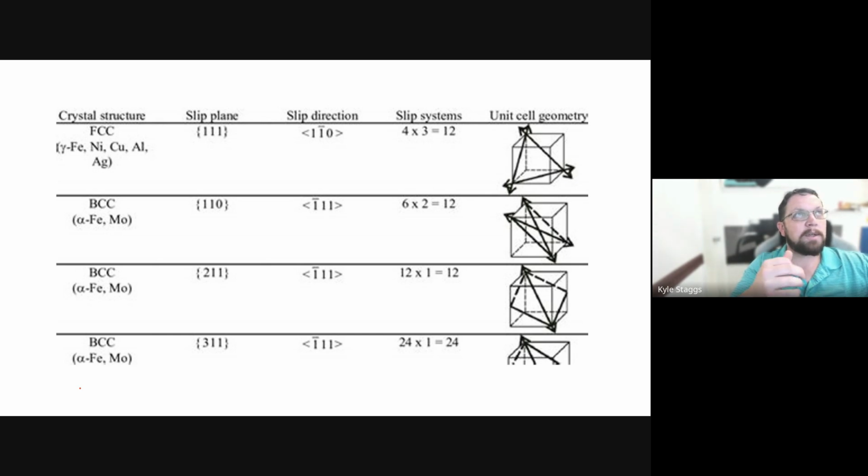But it's actually because of the jagged serrations that are going to show up at the edges of those materials because of the 111 slip plane orientation of those kinds of materials. So these actually can make for very effective cutting edges as a result. And anybody that's had a paper cut from a metal foil, I'm sure can testify to that.